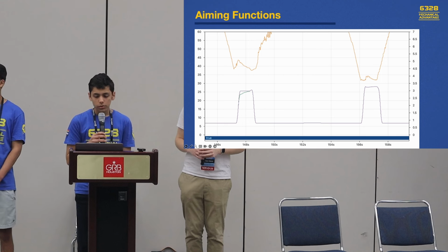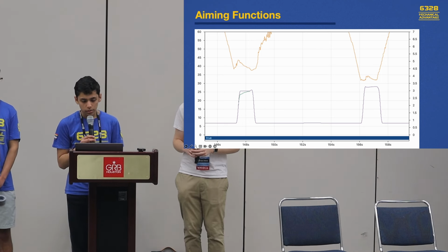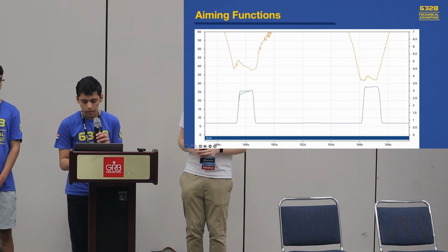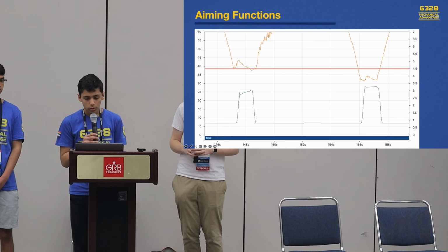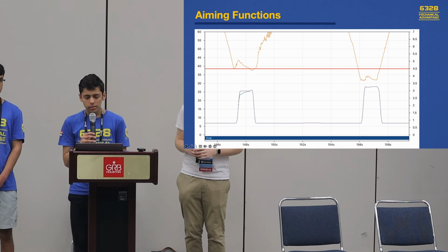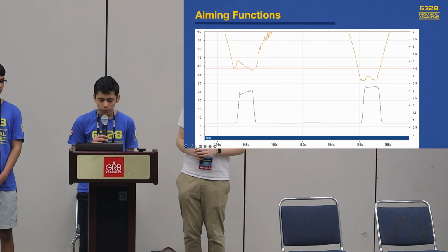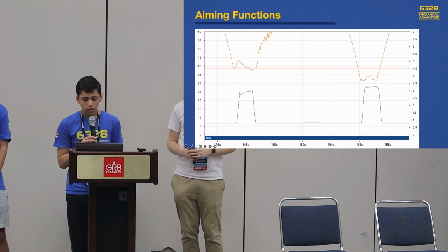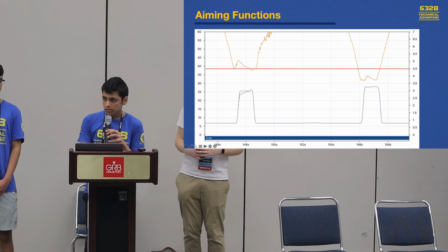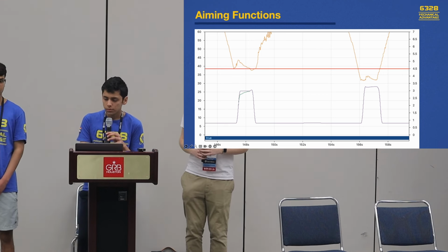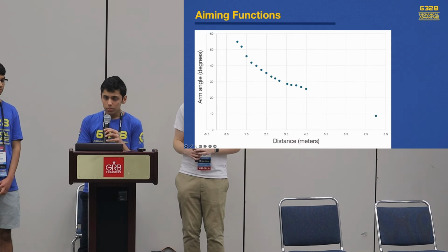Orange in this diagram shows the effective distance between the robot and the speaker in meters, and here's the cutoff of our original map, which didn't have the extra point at 8 meters. Purple in the diagram is our original arm angle, and green is the replayed arm angle. As expected, closer than 4.5 meters, we're still interpolating between the same points, so they match perfectly. But farther than 4.5 meters on the left, they differ. The original one is constant at 25.6 because there's nothing to interpolate between, and our replay extends further down. So we changed the arm angle for our benefit. But it's still not great.